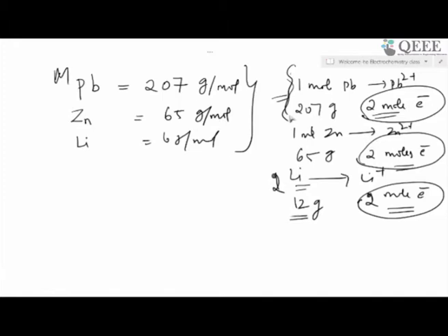The battery will automatically self discharge, and after self discharge it forms a non-conducting lead sulfate coating on the electrode surface that prevents the battery from starting again. So there are issues with that. So if you properly maintain, that means the maintenance is high on lead acid battery. But there is no such issue when it comes to lithium battery.